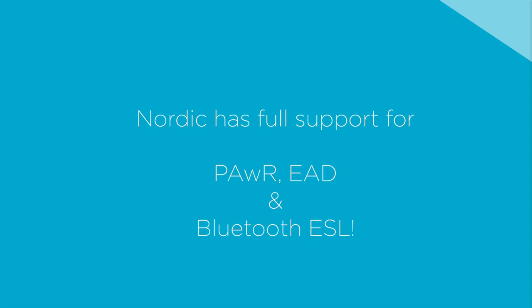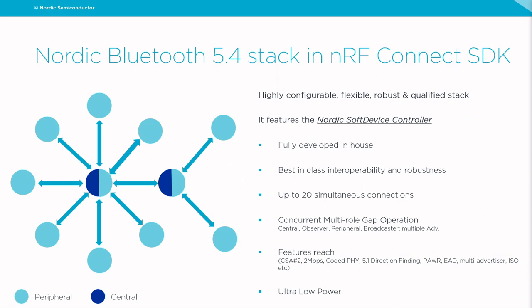After this simple demo, let's see what Nordic Semiconductor provides. The good news is that Nordic has full support for PAwR, EAD, and Bluetooth ESL. Let's start with the lower layer and then go up to the applications. The Nordic Bluetooth 5.4 stack is already available in nRF Connect SDK. This is a highly configurable, flexible, robust, proven in the field and qualified stack.